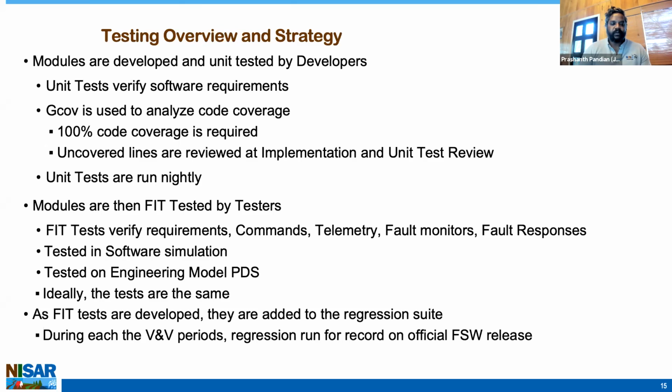And the other level of testing that I really want to mention here is what we call our FIT test, which stands for Flight Software Integrated Testing. And this is sort of our black box testing, and the idea is that this is sort of halfway between a software test and a system level test that might be done by a system engineer. So we use the software in addition to software simulation and also actual hardware in terms of the RAD 750. But the main goal here is to test software. So we're still sending commands and looking at telemetry, but we're not, for example, calling functions directly. And I think that this level of testing has been a huge boon for software in terms of finding bugs early on before we have delivered. Next slide, please.